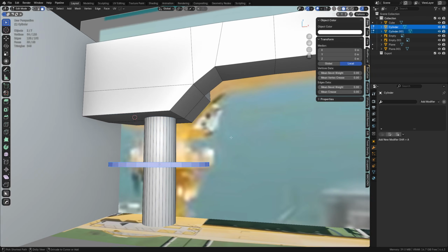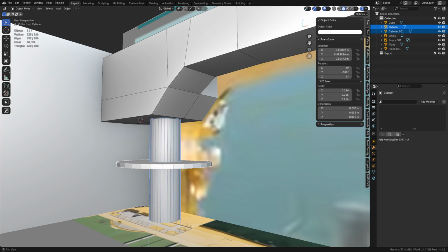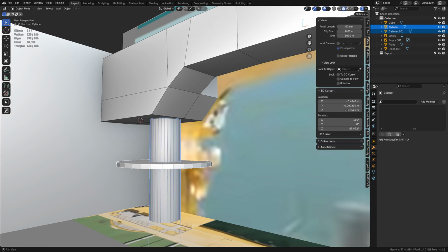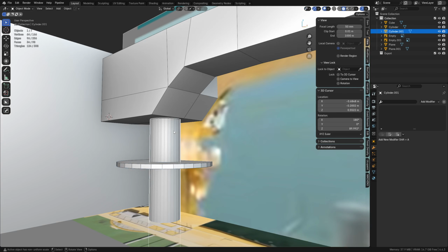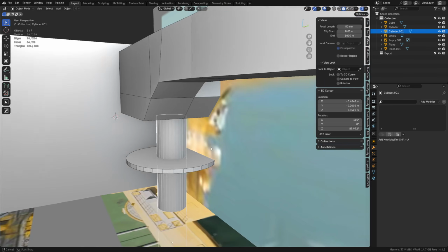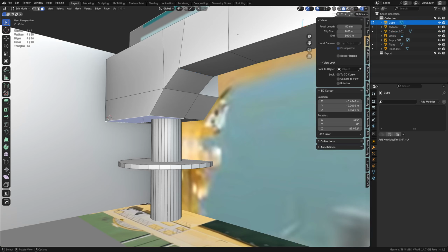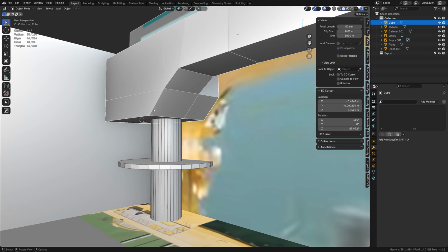Another thing you could do, which might be useful, is once you have the cursor position, you go to View. You see the 3D cursor here on Y. This should be a global coordinate. Copy that. When you grab this in object mode, it should be using global. So on Y, you should be able to paste it in there. Whoops, I guess I got that wrong. Hold on.